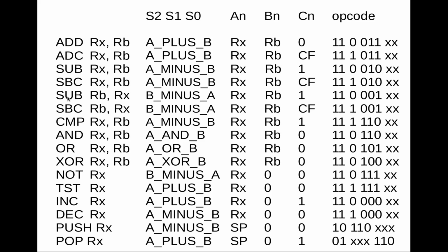And once again, we can do it once with the carry flag, with taking into account the previous carry or not. Finally, remember that for subtractions, because of the way our ALU works, if we don't want to borrow, which is what you do in the case of a subtraction, then we actually need to set the carry in to 1, because the carry in turns out to be exactly the opposite of the borrowing. So one thing to remember here. Now, of course, that doesn't really work for all operations.